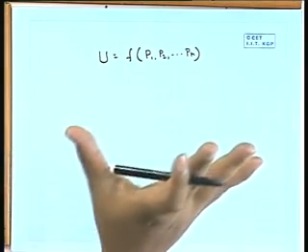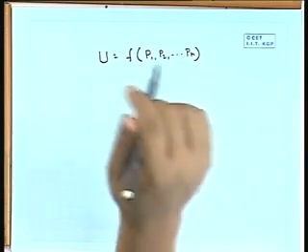So, there is a beam problem, it is subjected to P1, P2, P3, P4 like this. The bending moment for the different regions you can express in terms of P1, P2, P3, P4, Pn, because the reactions will be in terms of these forces, and the reaction into that distance, the force into some distance, automatically the moment expression will be in terms of P1, P2, P3, P4, Pn. The energy expression is nothing but the integral of M squared by 2EI dx. So, the whole thing will be expressed in terms of these forces.